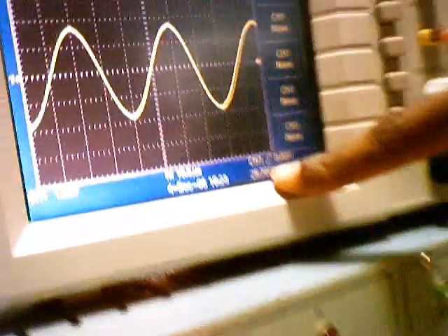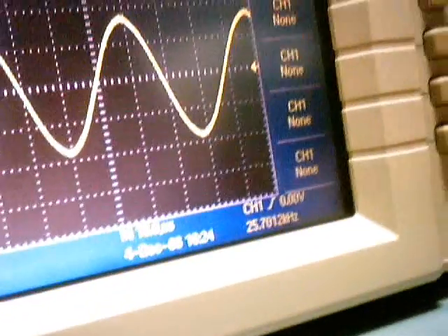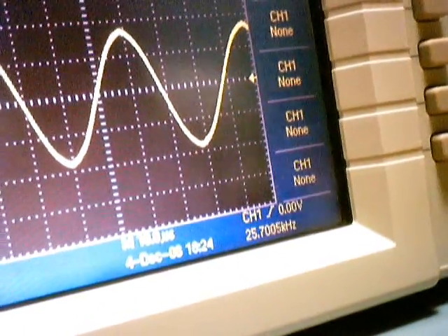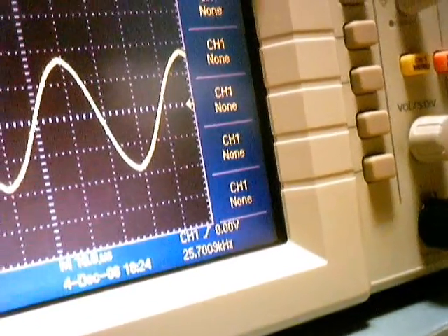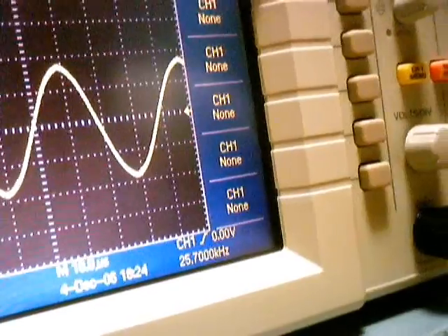So what frequency have we just kept? The input frequency is around 25 kilohertz from your DSO. Does 25 kilohertz happen to be in the passband of your high pass filter or not? So can we keep a frequency anything other than 5 kilohertz, something like 50 kilohertz, 100 kilohertz?